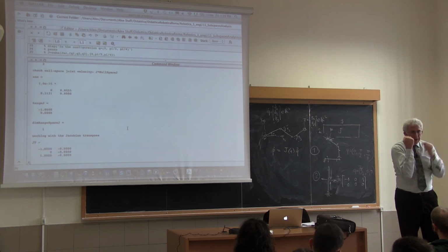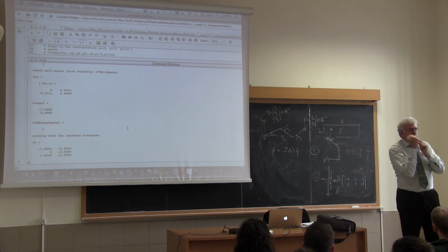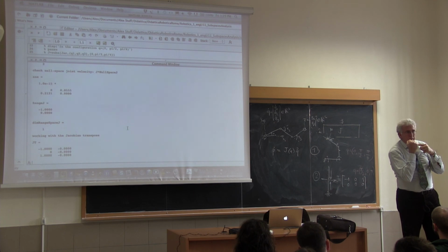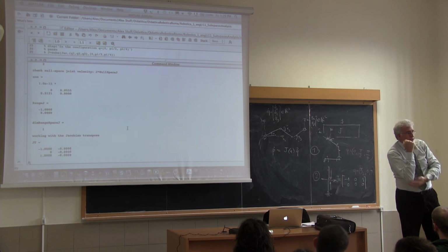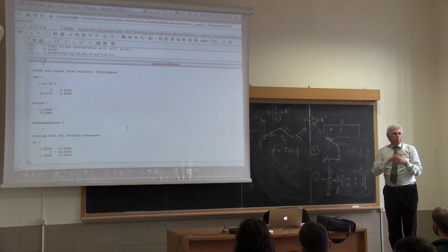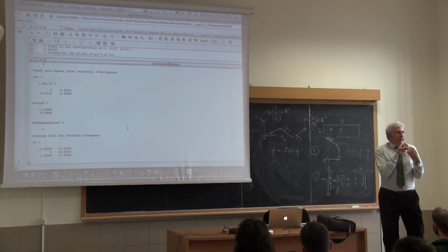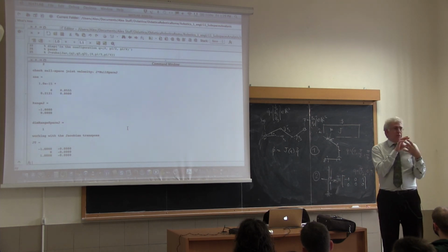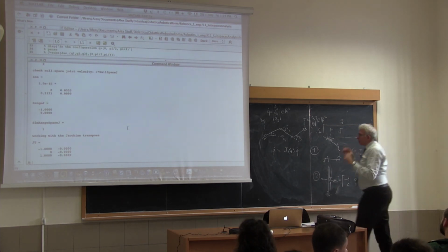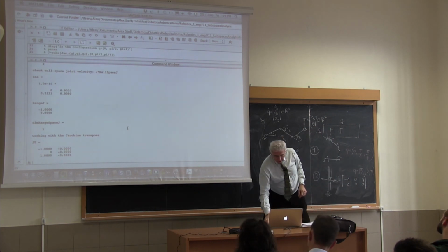You see the point? If I'm pushing here, the robot will move unless I apply a torque which keeps it in balance. If I'm pushing here, the robot will not move, and I don't need to add joint torque for balancing, because these forces will be balanced by internal reaction, by the fact that the robot is a rigid body. Okay, so this follows from this simple analysis.